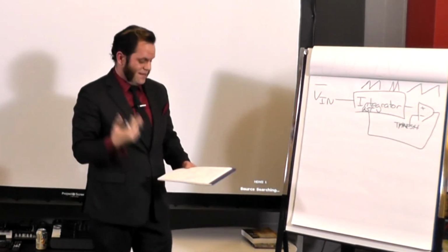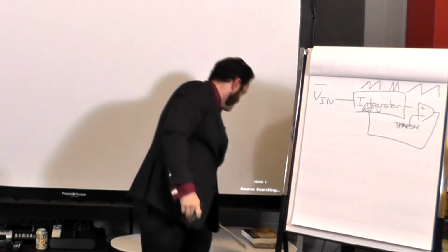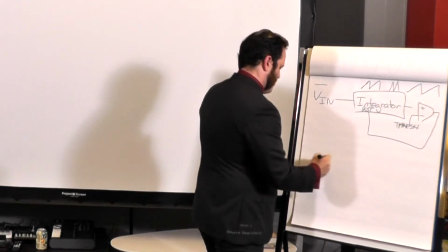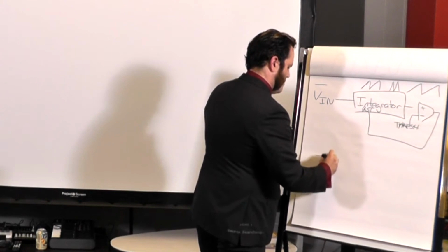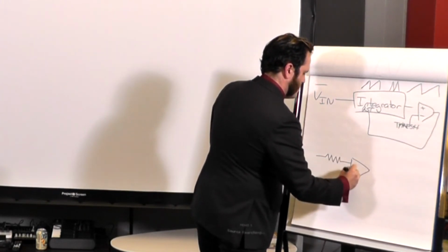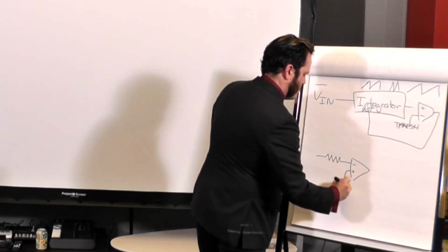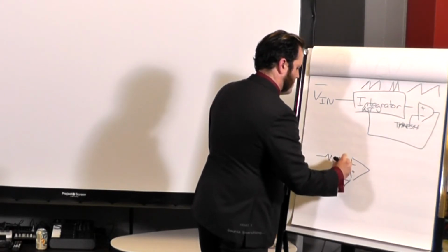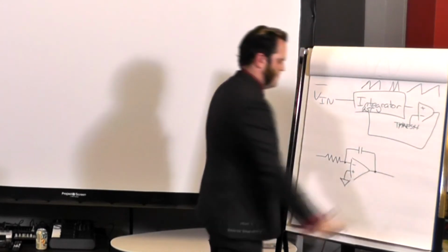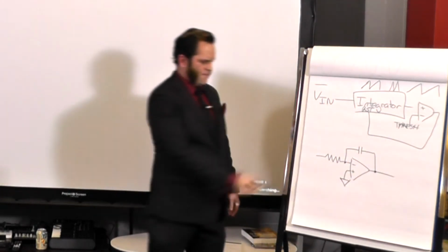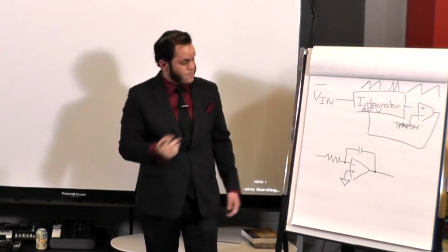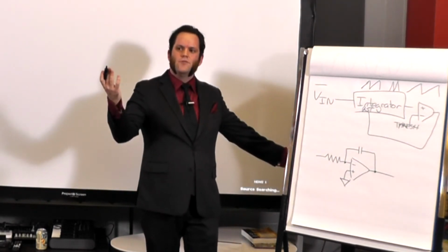And it turns out this is really, really easy to build. The most basic integrator of all is that guy, right? We have a voltage input here. This resistor turns it into a current, starting to charge up the capacitor until the op amp can do no more.